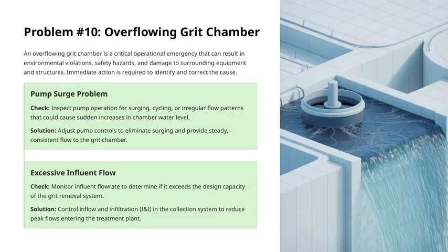Another factor to consider is excessive influent flow. We need to monitor the influent flow rate carefully. If it exceeds the system's designed capacity, it can overwhelm the grit removal process.